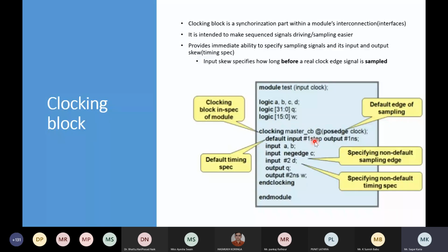What are the input and output of the testbench, not of the DUT? Remember that. This is all on the testbench side that I'm talking about. I'm not talking about anything on the DUT side, because your clock would be generated from the testbench, not within the DUT. DUT is just design specific. It's just a behavioral code of a functionality. It doesn't create anything, right? What is the need of a testbench? Providing the stimulus, providing the data, providing the real test scenarios, test vectors to the DUT.